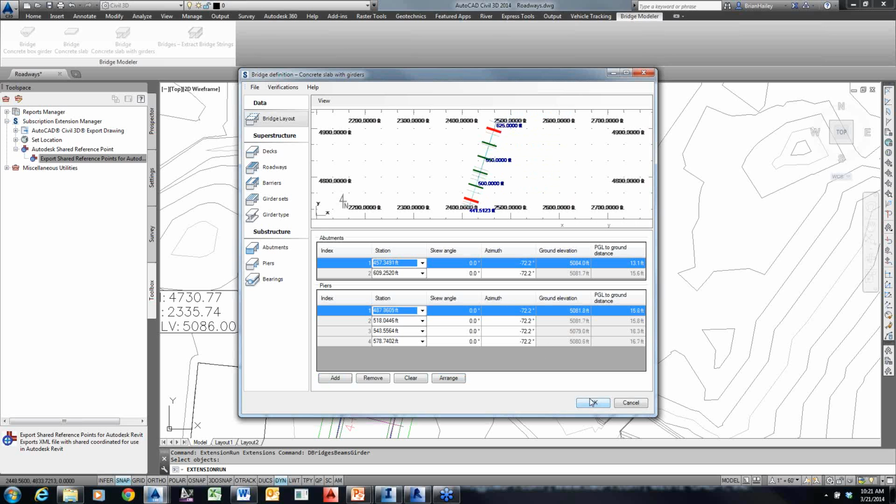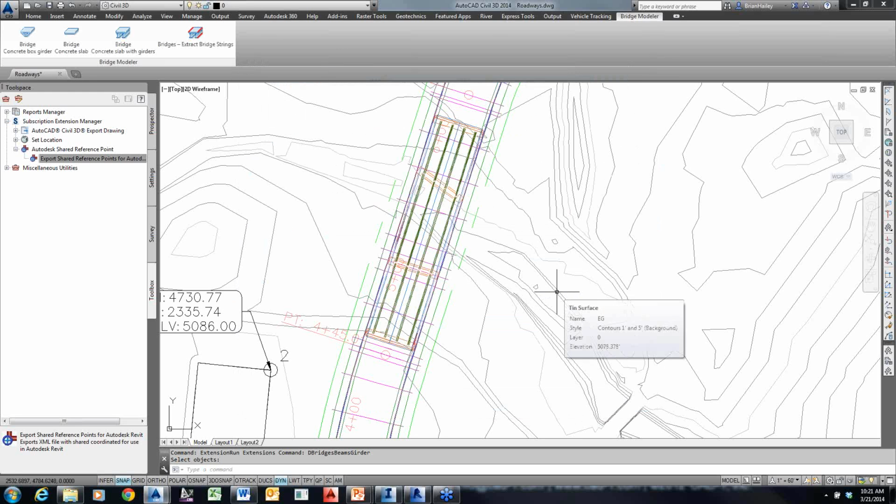But one of the reasons you have to kind of look at is that the dialog box is actually talking to two separate programs, and two actually very different programs with Revit and then Civil 3D. So that's part of the reason you can't make the picks in the native program. You have to have an interface between the two. And in addition to that, all these different solids in here or components in Revit are connected together, and so it's adjusting not only the piers and stuff, but each individual support member for the bridge itself, and kind of arranging everything. You can see there each beam is split at the pier level, so it's got a number of different parts that are being arranged at the same time.